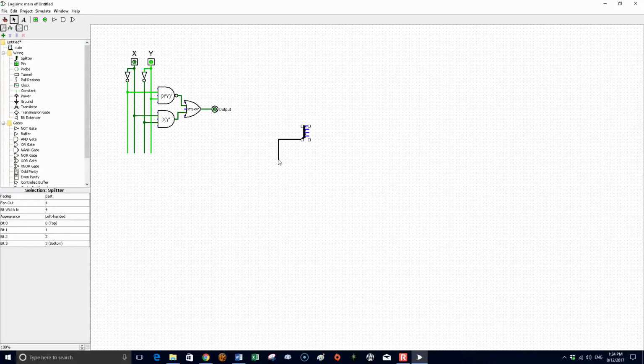If I now try and connect this over here to this wire, everything turns this orange color, and a 4 appears here, and I see a 1 here in other places. The problem is, this is expecting a 4-bit number, and this is sending a 1-bit number. Those don't match, and so down at the bottom here we get the error incompatible widths. Also, notice this is turned red. That's because we don't have anything sensible to send out, so nothing is being sent out here. There's no longer any information being sent, and we get an E in here for an error.